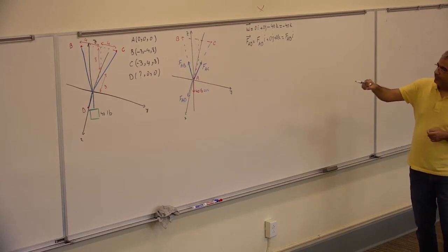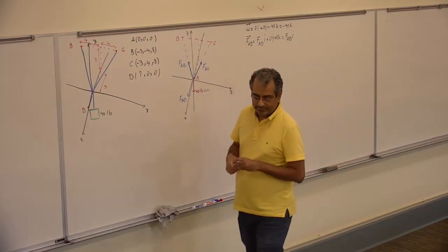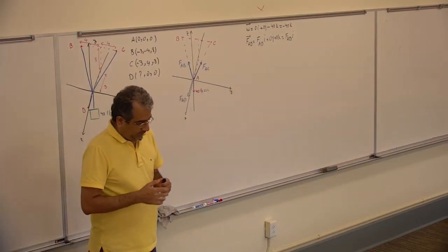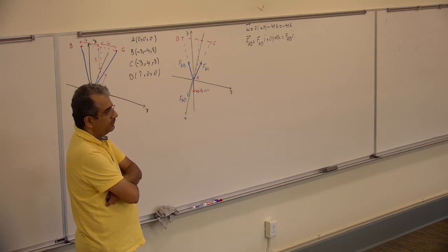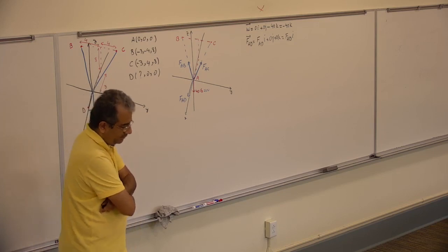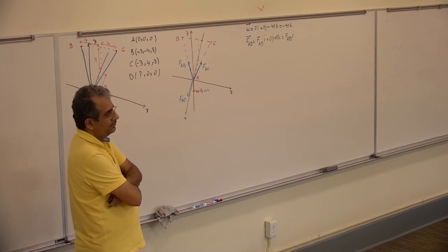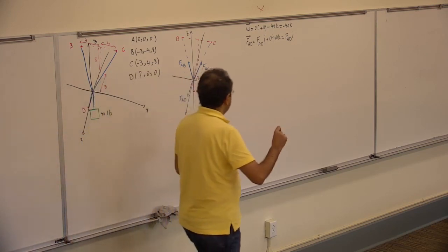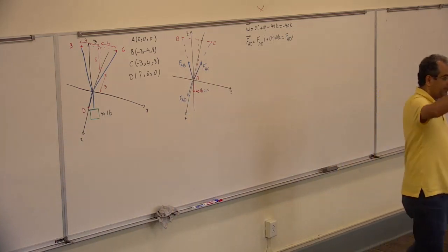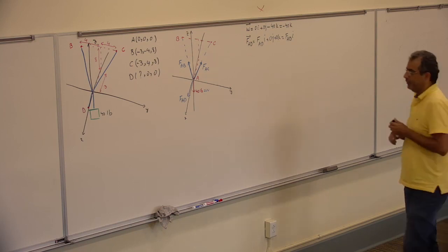But what about the FAC and FAB? Oh, we already graphed, put everything in the coordinates, so wouldn't it just be, for FAC, negative 3i, 4j, 8k? Because that's its coordinate points. You can't use that. You have to find, remember that? You have to find the position vector. Yep. And then from the position vector, find the unit vector. And then from there we can get the force.